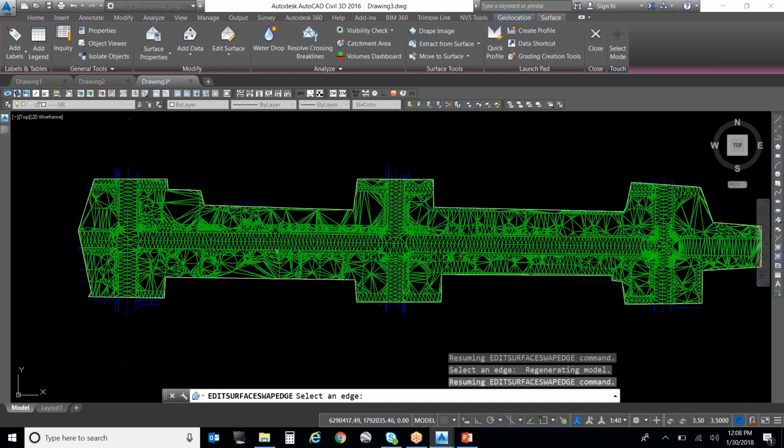So if you have a good concentration of data here at this intersection, and your whole job is all about just this intersection, then just supplement the information in that intersection, okay? You don't need to supplement everything, okay? Let's say that you just had to supplement here and supplement here because you're doing two center islands, okay? You supplement just for those islands. You don't have to supplement the whole thing, okay? But our preference is that you cut and paste the stuff in rather than try and supplement this information.